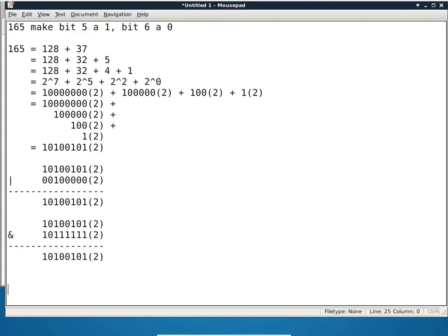Now, when you use a bitwise exclusive OR, it is useful for toggling something. Okay, if it's on, you turn it off. If it's off, you turn it back on, which can be useful. For instance, if you have an LED and all you want to do is to blink it, to toggle it. So if it's on, it becomes off. If it was off, you want it to be turned on, then the exclusive OR operator would be useful. Very good.